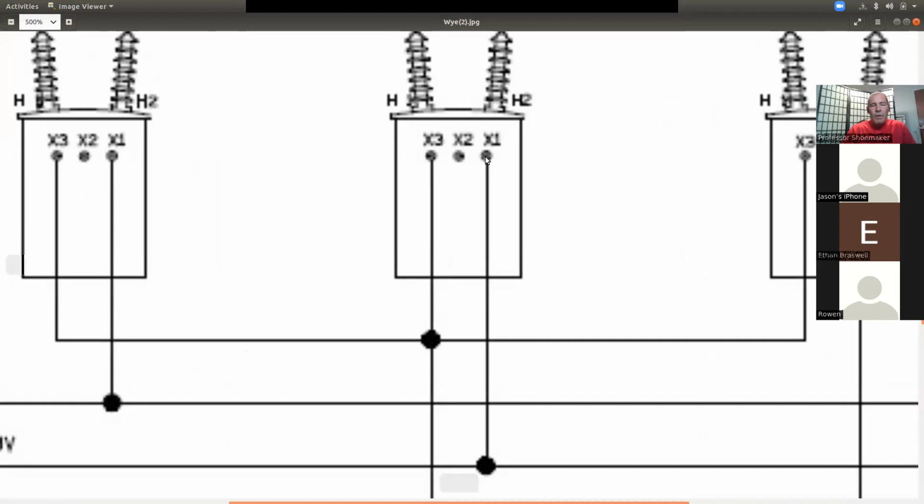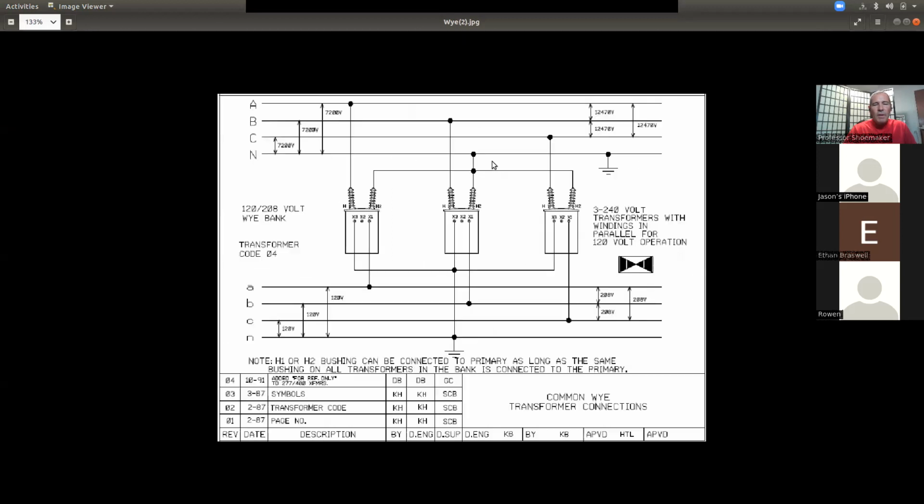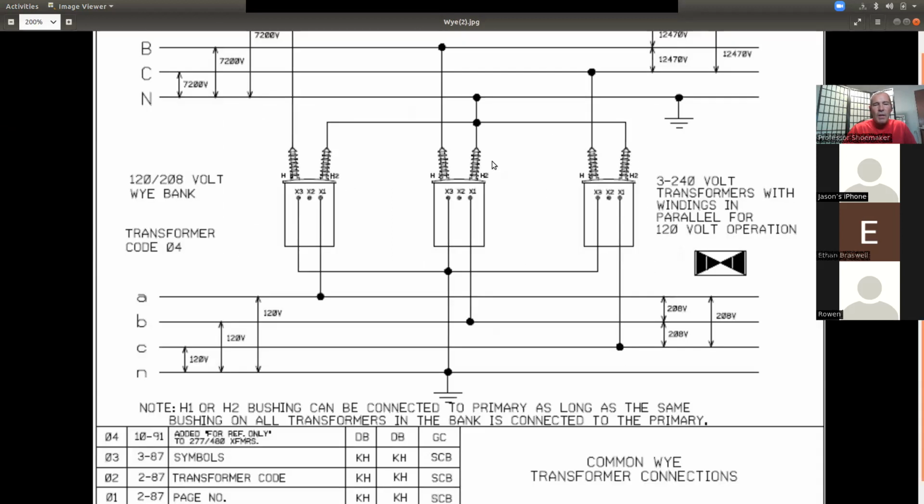You're going to convert it. The AC lead over here stretches over to the bushing, and you just tighten the nut down inside the transformer, and BD over here. Some companies, Santee Cooper does not, buy the transformer pre-made. It's a 2 bushing transformer, so it's already done for you. But of course, we're going to teach you the hard way.